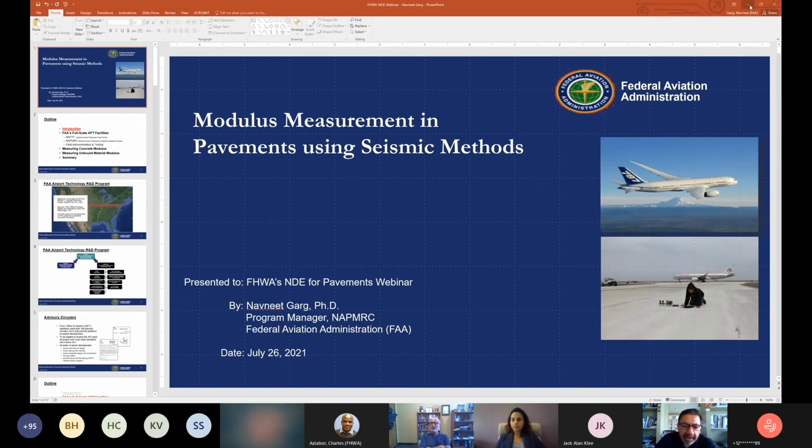There was another thing I would like to add. We also used PSPA on asphalt pavements, and there also the results were very repeatable. One thing that we tried but couldn't do: once the asphalt paving is done, we know the temperature is falling. So let's see if we can measure the modulus at that time, and if we can develop a master curve kind of thing. That was something we could not do because the material properties are changing so fast as it's cooling. We had a hard time getting reasonable, repeatable values. But once the pavement cools down, the results were very repeatable and reasonable.